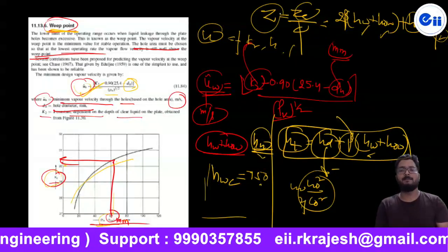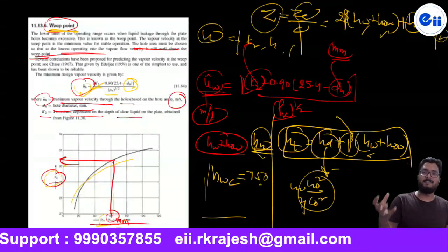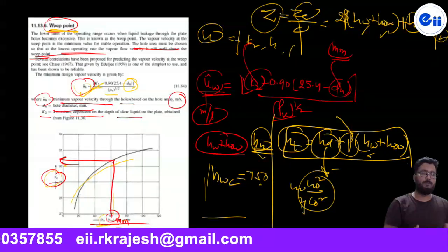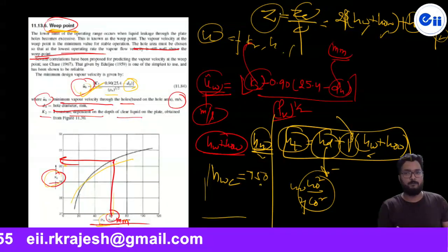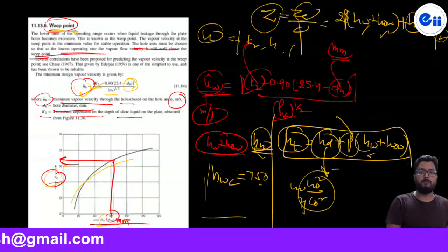तो वहाँ से क्या आ जाएगा, Z आ जाएगा, 5 होता है 0.5 आपको पता होगा, 50%, जो कि एरिएशन का फैक्टर जो होता है. आई टोल्ड यू क्लियर लिक्विड तो होता है, बट जो एक्चुअली कॉलम में लिक्विड इज एरिएटेड लिक्विड फ्रोथ होता है, दैट्स व्हाई डेंसिटी ऑफ द फ्रोथ विल बी लो एंड दैट्स व्हाई हाइट विल बी मोर. तो इसलिए हम इस फैक्टर को भी ऐड कर लेंगे.